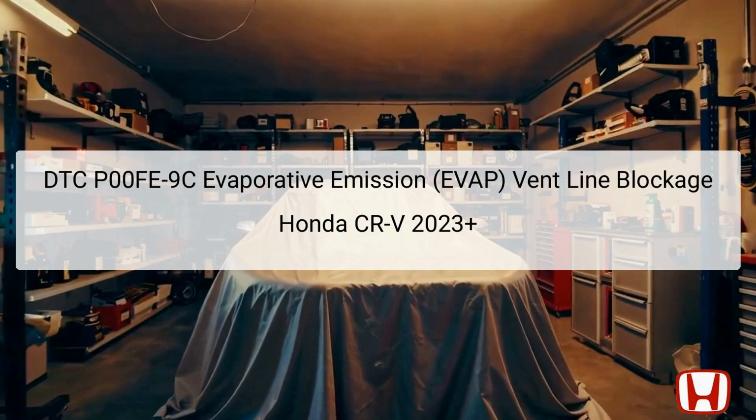This system consists of several integral parts, such as the fuel tank, EVAP canister, and the EVAP leak check module. If there is a blockage in any part of this system, the PCM considers the volume of the EVAP system to be below the required specification, prompting this DTC to be stored in the vehicle's memory. Understanding this code entails knowing the functionality and interconnections of these components, as any obstruction can lead to performance issues or increased emissions, thus violating environmental regulations.